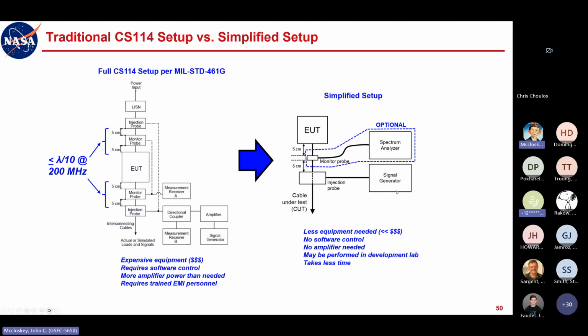And one advantage to this is that the signal generator setting we need, as I'll show you on Wednesday, to get the 3 milliamps is generally about 108, 109 dB microvolts, so a little bit less than 300 millivolts, right? 120 dB microvolts is 1 volt RMS. And that's into a 50 ohm load.